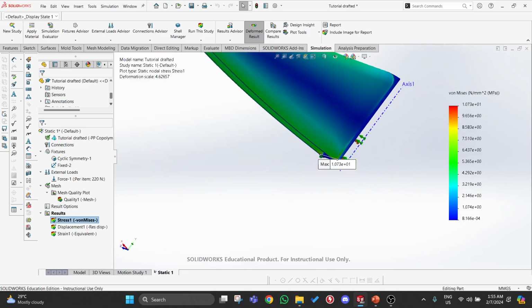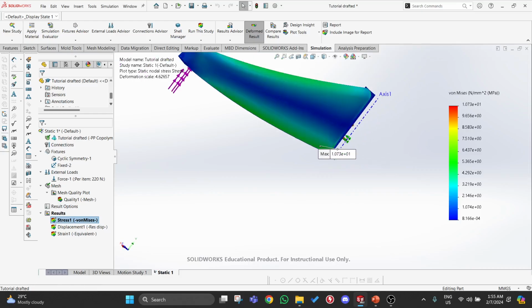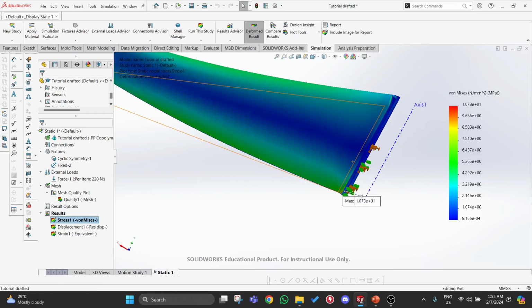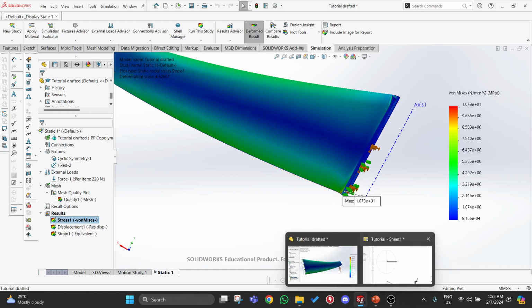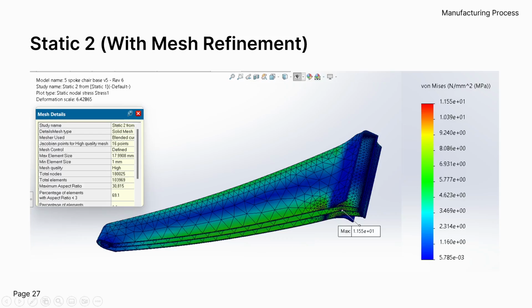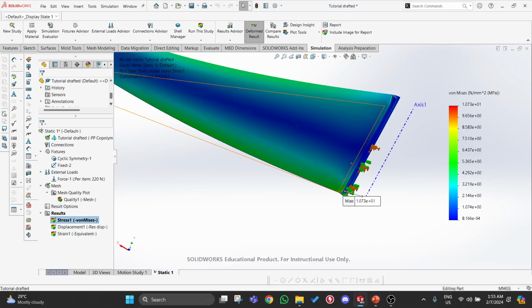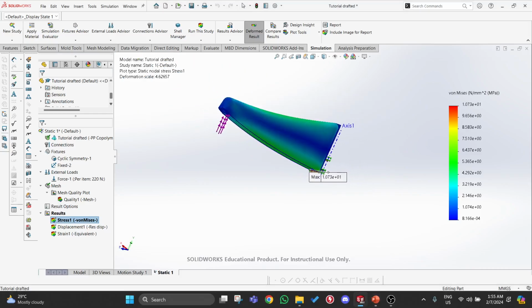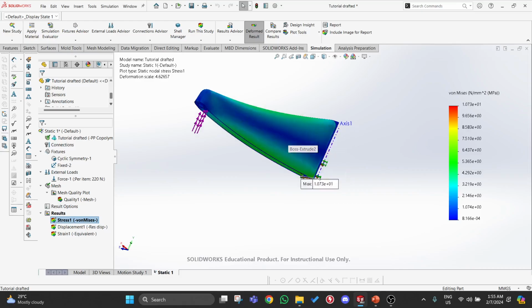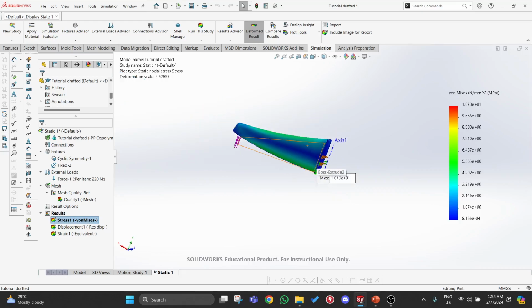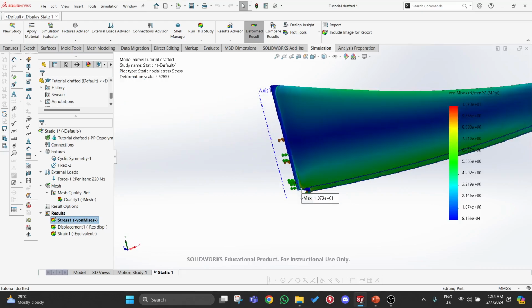So is there a way to solve this issue? Maybe if I lower it down, it's going to lower the height here and decrease the stiffness. With this moment of inertia formula here, it's going to decrease the moment of inertia, but it might increase flexibility, more displacement. Maybe that's a solution, who knows. There's a lot of ways to tackle this, and in this case, being able to find the source of the problem helps.